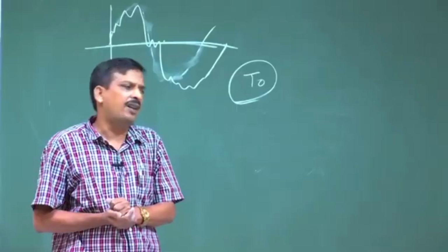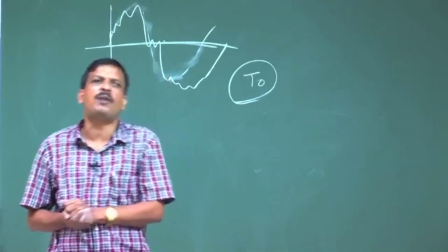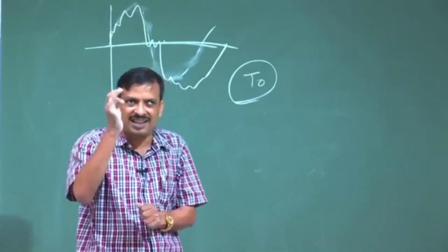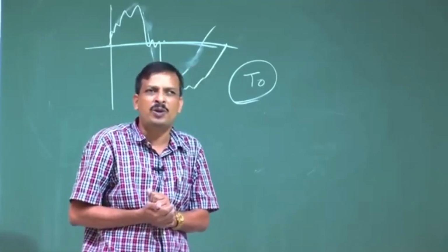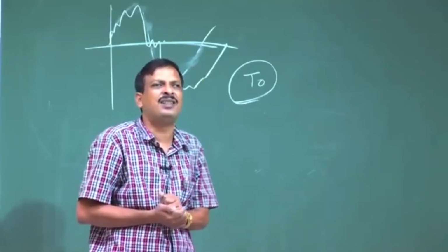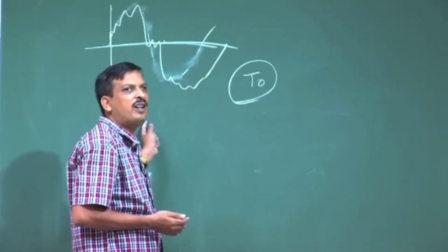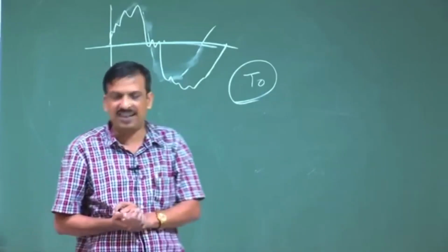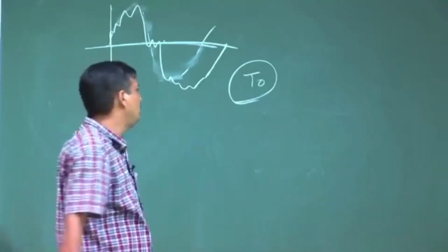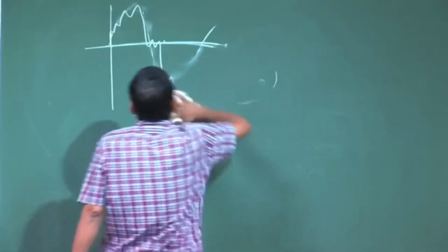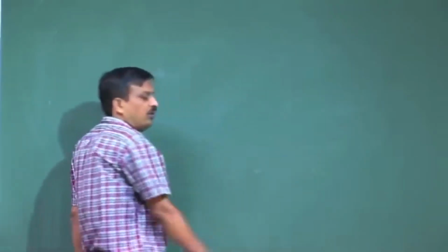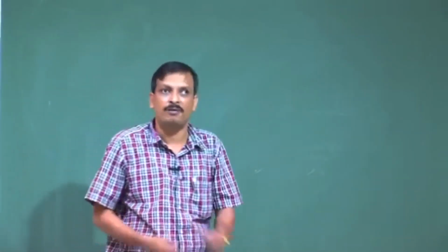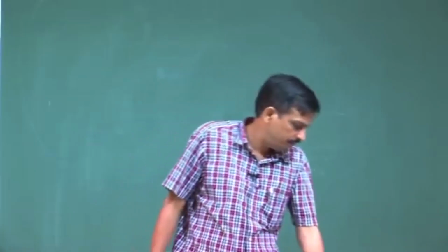Okay. But if you see, detecting the number of zero crossings is the easiest algorithm. So, the time complexity of computing F0 is very low, but it is not at all noise robust. So, I can say the zero crossing detection method for F0 extraction is not that useful, or you can say it is not reliable. Okay.